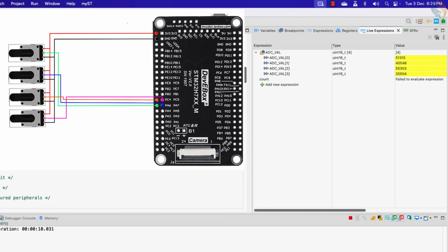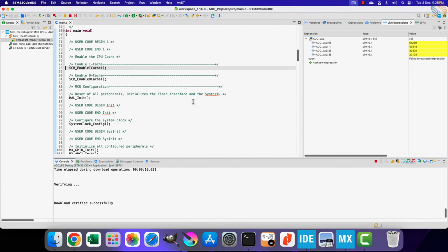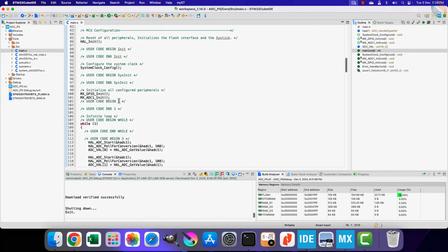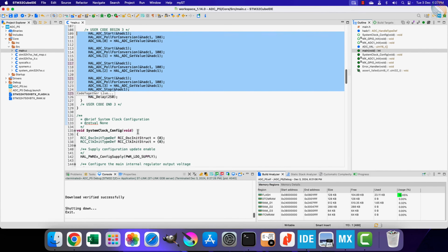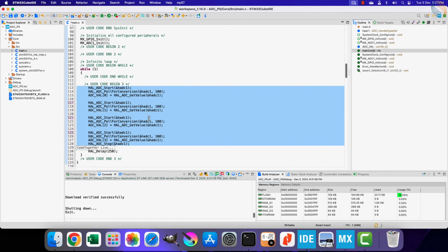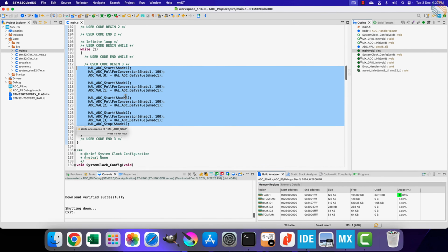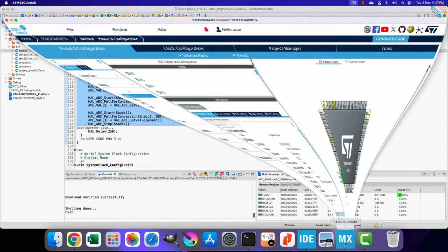So we were able to read multiple channels using the polling mode, and without the use of the DMA. Although if you see the code here, there is no point of doing it this way. Since we have to read all the channels anyway, so why not simply use the DMA? We can stop the ADC after reading just 2 channels, so the rest 2 channels can be avoided, but if you want to get the data from the third channel, you still need to read the first 2 channels.